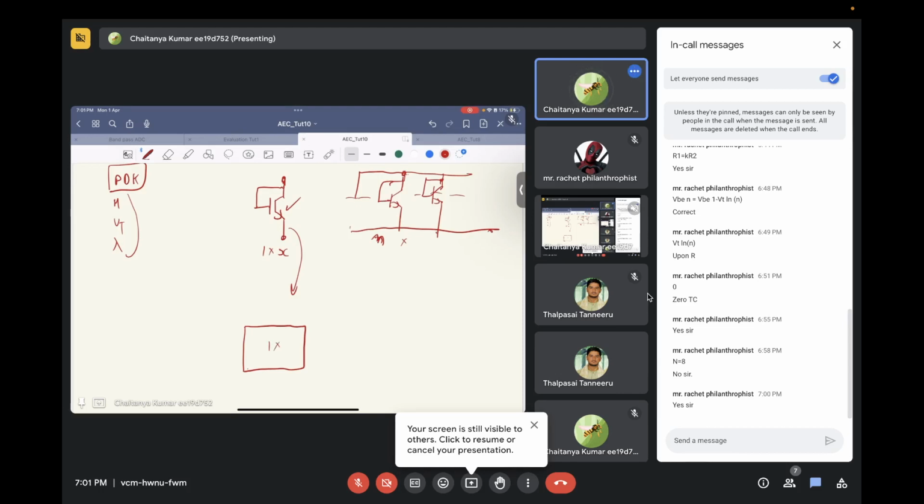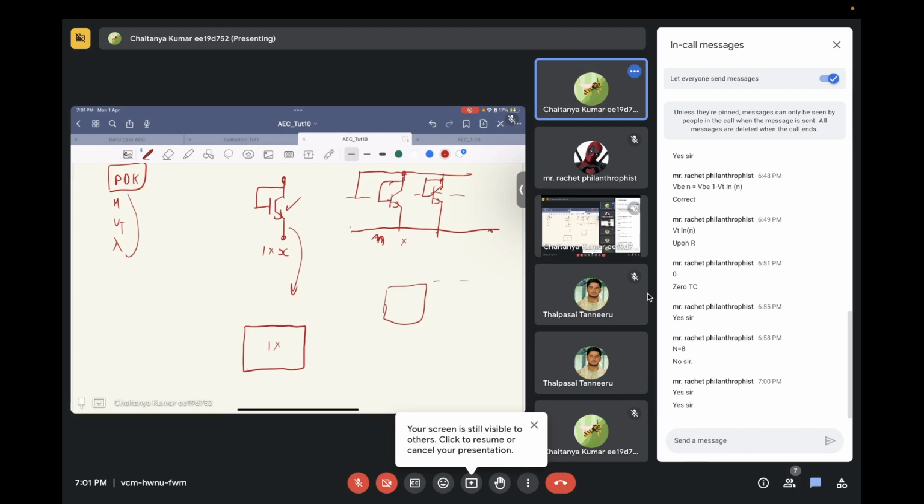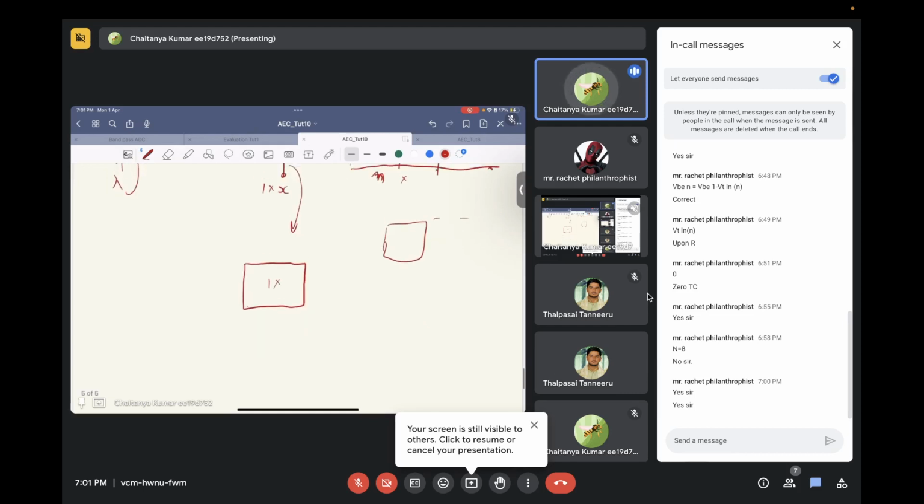So this is basically the layout of this transistor. For the nx device, how will it look? It will basically look like 8 of such squares connected with each other. You understand? In layout, what you want is symmetry, so that the circuit is symmetric both about the x-axis and y-axis.